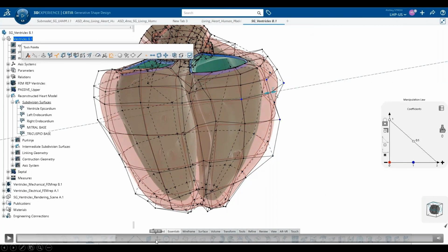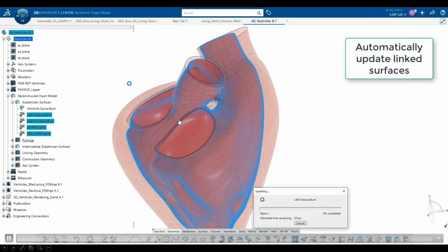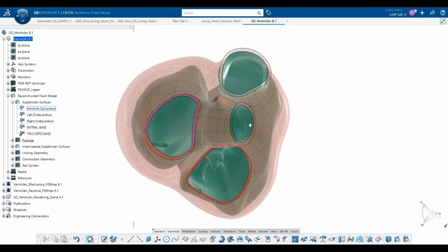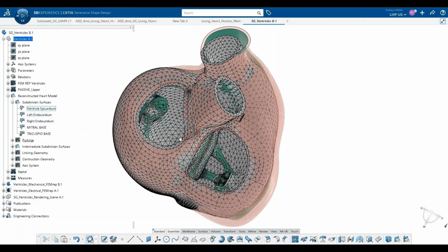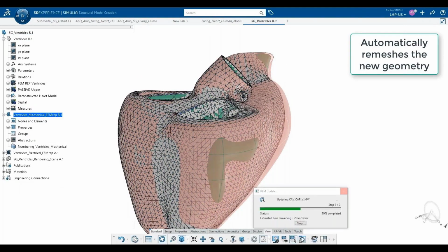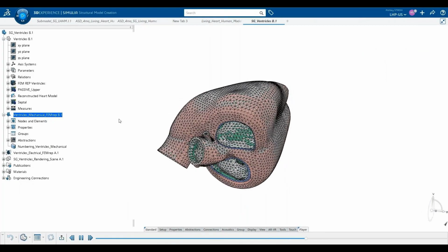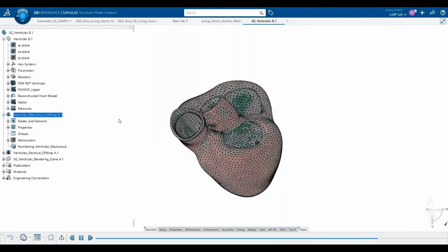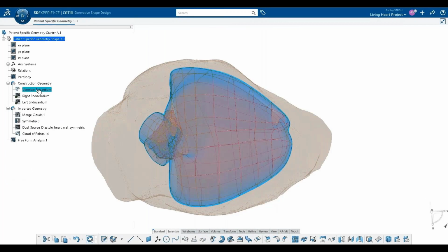And so as we're manipulating this model, all of these surfaces are connected. So I'm just going to pause it right here. All of these surfaces are connected and stay together. And so once we update that model, our local wall thickness stays the same. And if we want to change our local wall thickness of any of these regions, we can pull on that green surface instead of the pink surface. And this is really the purpose here, right? So all we have to do is just update, and the mesh is a high enough quality that we don't have to worry about any of the thin meshes failing, just because the local mesher reruns, and any of those local meshes stay in high quality, right?